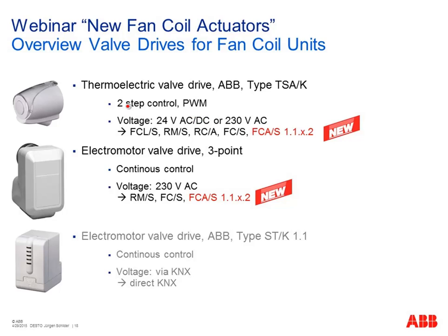And we have a lot of components to operate such an electrothermal valve drive. And here our new fan coil actuators, of course, as well. First of all, only the name here, but I come to some more details later. Furthermore, we have these so-called electromotor valve drives with a motor inside, and we need 2 contacts to open or to close the valve. For electrothermal valves, we need only 1 contact. So both are connectable to our components. And as before, a bit more precise positioning and a bit faster reaction is possible with electromotor valve drives.